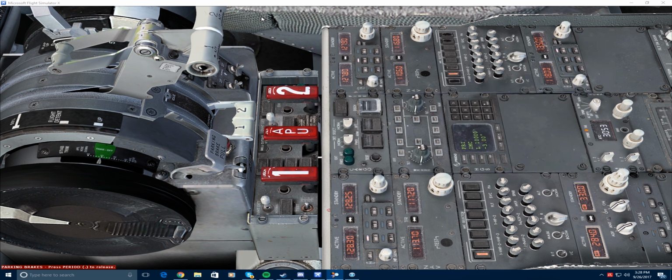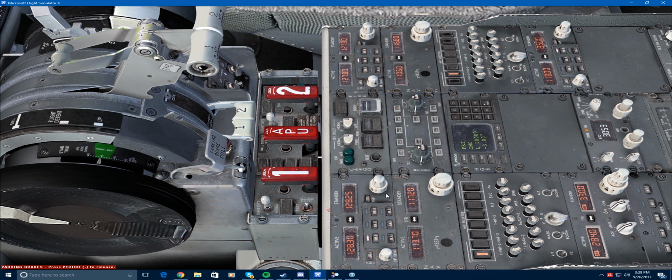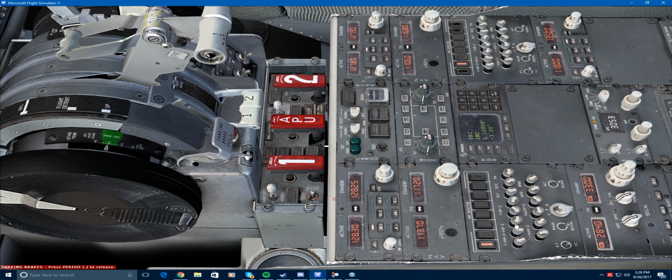So because of that, I'm going to go to what's called Unicom, which is just universal communications. You don't have to go through anything with air traffic control. You just communicate with other pilots within your region directly. The frequency for that is always going to be 122.80, so I'm going to set both of my radios to 122.80. I'm going to switch that to active on both sides.